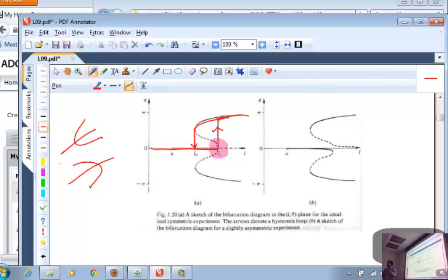So there are a lot of parameters in the problem: the tilt, the distance between the two holes, the stiffness of the material. They will all determine what the response is. The response can be very complicated. Now, the same thing, if you, for example, tilt it, you might find the connectivity change like this. Whereas the top one remains stable but becomes disconnected, and the lower part being unstable. So here now we have three limit points. This one will be called a fold or a limit point. This one will be a fold or a limit point. This one will be a fold or a limit point. And we will see later on what happens at the limit point.